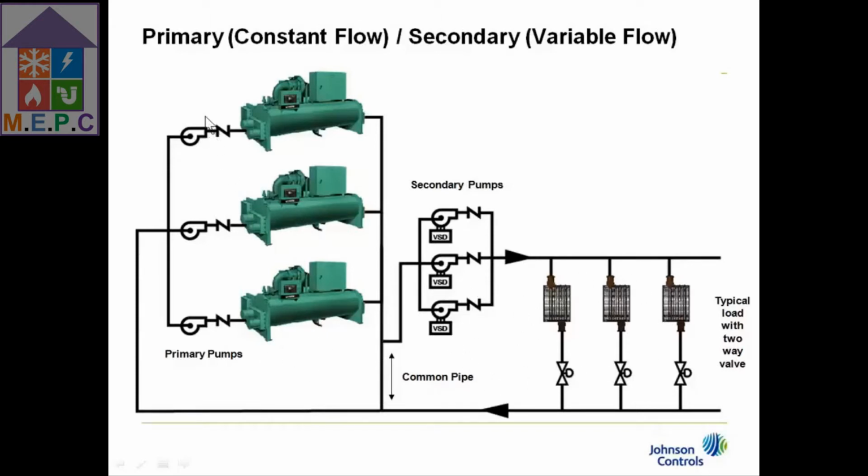You'll notice that we have a dedicated pumping arrangement. That doesn't mean that primary-secondary doesn't come in headered pumping as well, or a combo of the two. It's just that most of the time I see dedicated type pumping.